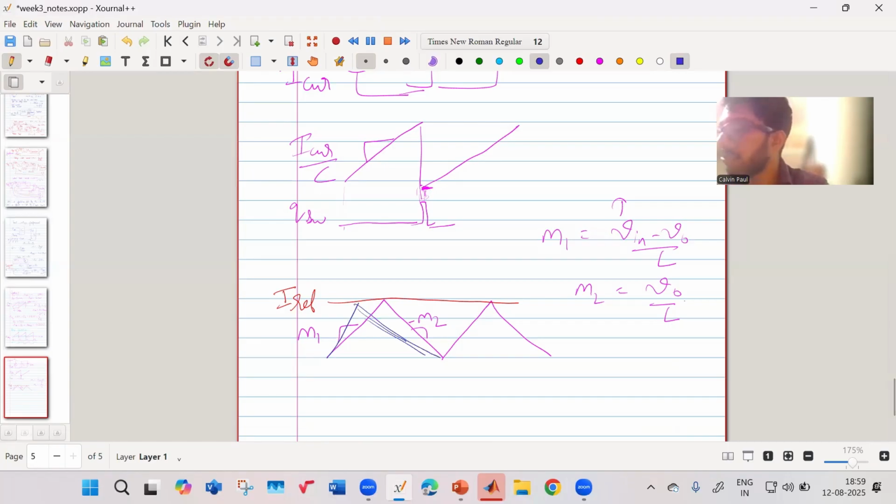It will be like this, something like that. Okay. So this slope will change. So I don't need to have this current source and all this thing to multiply it proportional to input voltage, etc. The inductor current itself has that information, the slopes, as the information of the input voltage having changed. So current mode control has that inherent information of the input voltage.